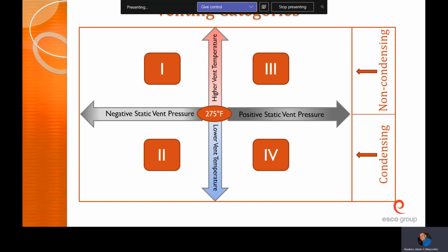So you might think, well, why couldn't you run PVC, or why couldn't you run metal with all of them? Because if metal will handle higher temps, then it would handle lower, right? And so you may think, well, why couldn't you run a 90 plus through metal vent? A condensing gas furnace is running right on the borderline of condensing. Even though a lot of it condenses in the furnace, as it goes through that pipe, any flue gas, any water vapor that makes it into the vent, once it cools down just a little bit, is going to start to condense as well. So you have to have a way for that water to get back to the furnace and be drained out.